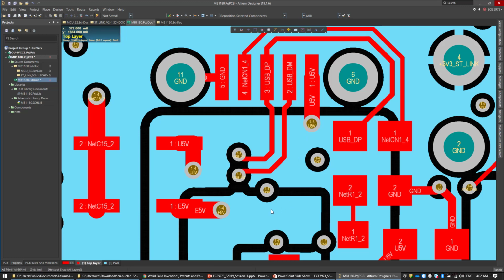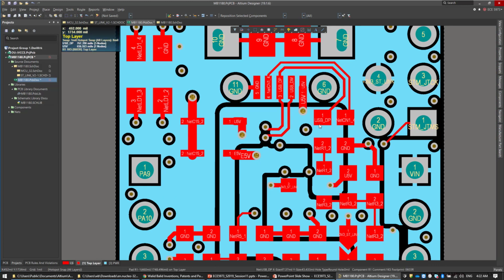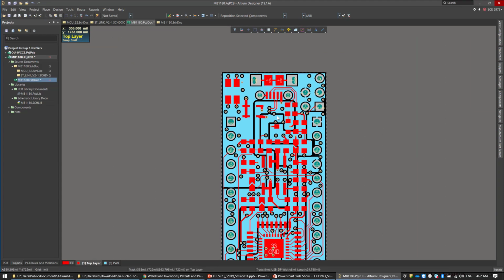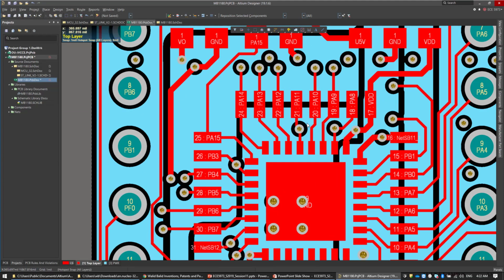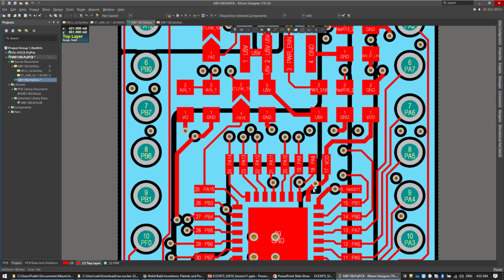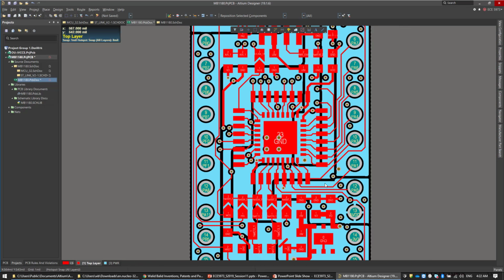Branch and connect inside. They could route it from here, come over here and here, but basically you are distributing the noise, the power supply noise, over the whole board. You really don't want to do that. You want to get this as short as possible, connect with the inner plane, and the inner plane is very close to the ground plane, and they will help to reduce the noise of your signal and make your design very robust. So this is the general guidelines you can follow when you design a 4 layer PCB.